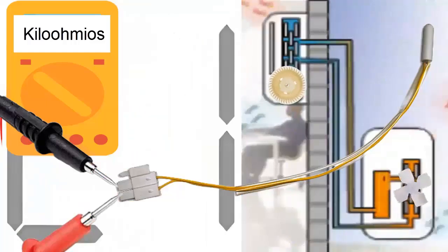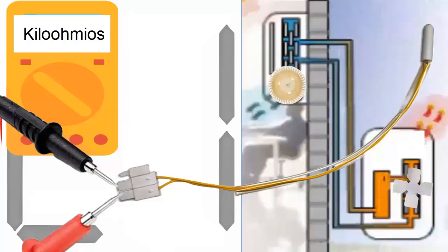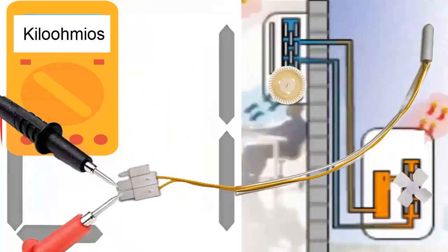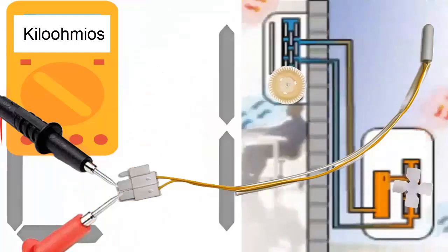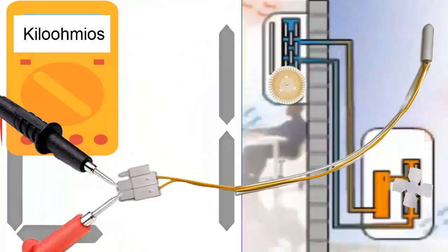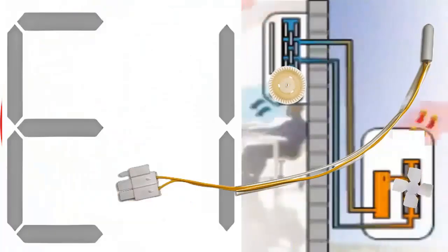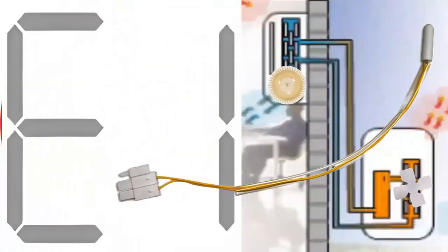For example, for many devices, at a temperature of 25 degrees Celsius, the resistance should be approximately 5 kilohms. However, consult the resistance temperature table for other values, and compare the resistance value marked on the multimeter with that of the table. If the resistance is outside the normal values, the sensor is defective and must be replaced.